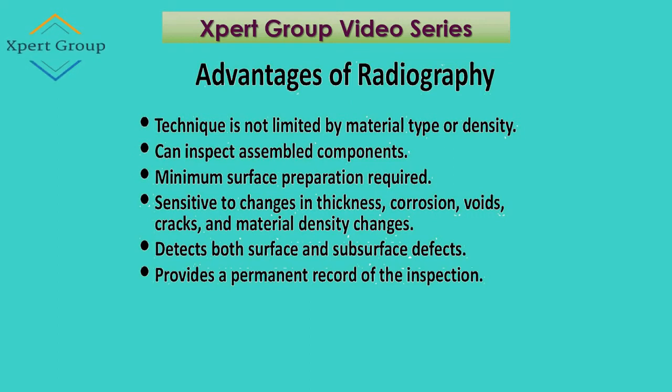Students, this technique is not limited by material type or density. You can use radiography on every material, of every kind of density. Secondly, radiography can be used for inspection of assembled components. You need not remove the component from a particular area.